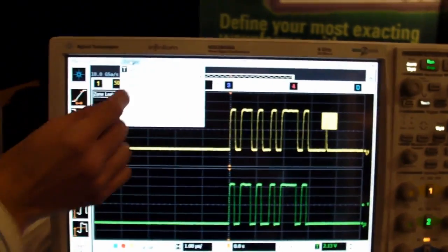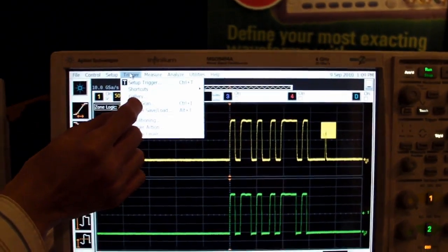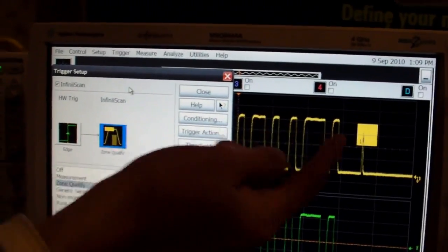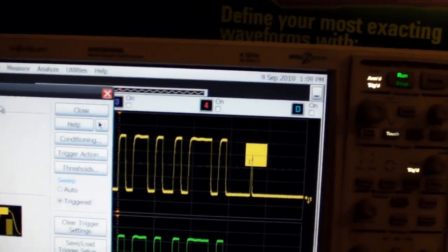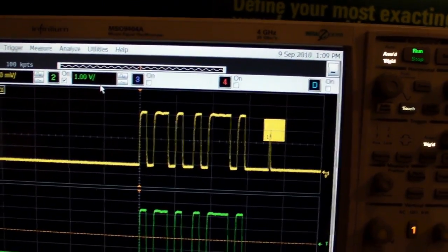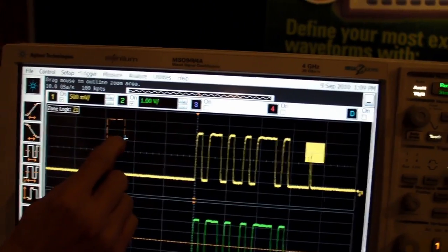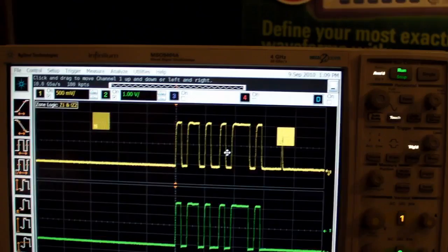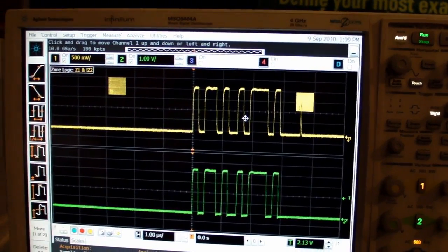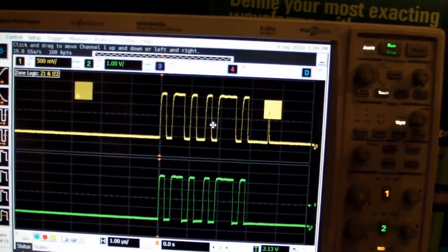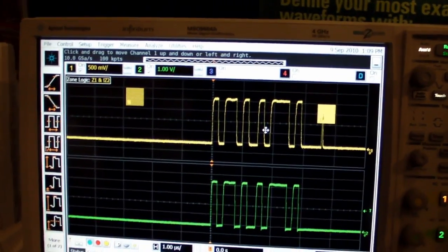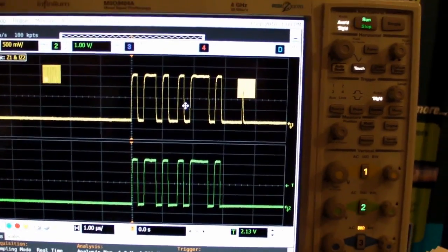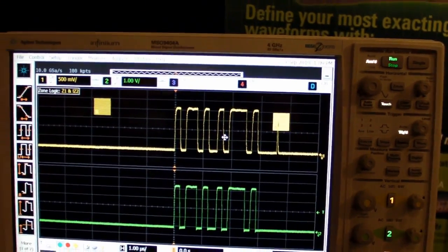So that means that you're getting a 2-stage trigger. So if I go back to the trigger menu, you get the edge trigger. Yep. And the second will be the zone qualifier. Got it. Software trigger. Yep. Fantastic. Very nice. And you can draw up to 8 zones. 8. Yep. You can have 8 separate trigger zones at the same time. That's right. Fantastic. I don't even want to know how much actual processing goes into triggering 8 zones at once, but that's very impressive. Excellent. Thanks for that, Tristan.